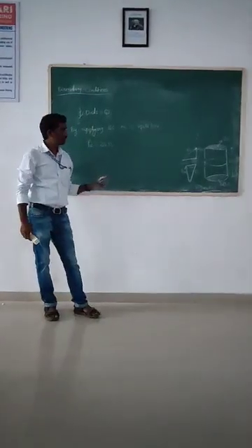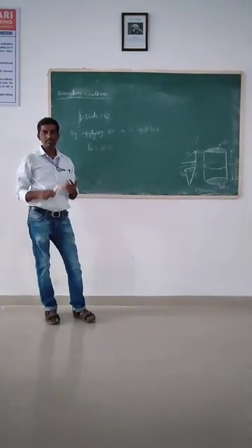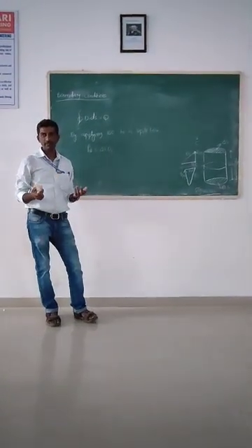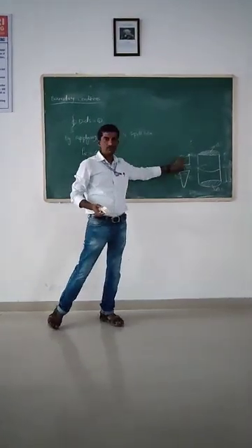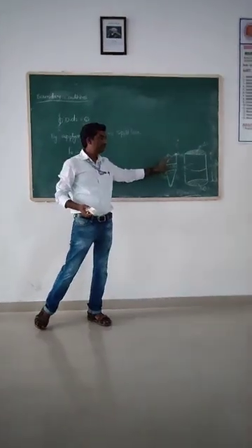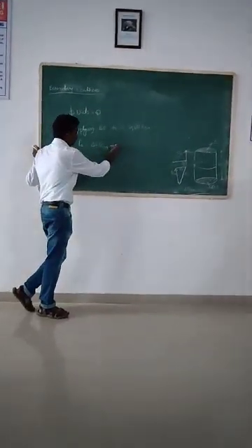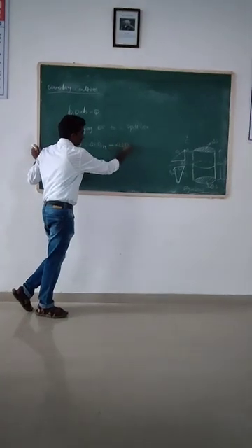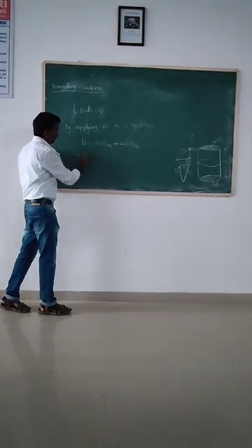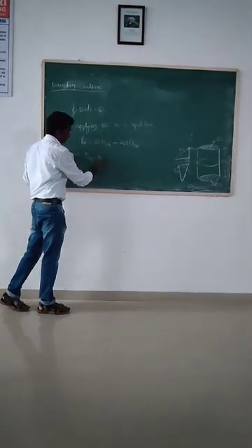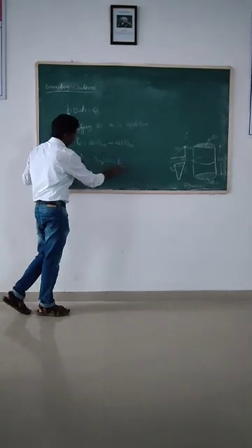Here the tangential components will be removed because of the symmetry, because it looks equal in all directions. So the tangential component of D will vanish. Only the normal component of D exists here. So we consider D1n minus delta S D2n. So from this we can write D1n minus D2n into delta S equals to rho S.